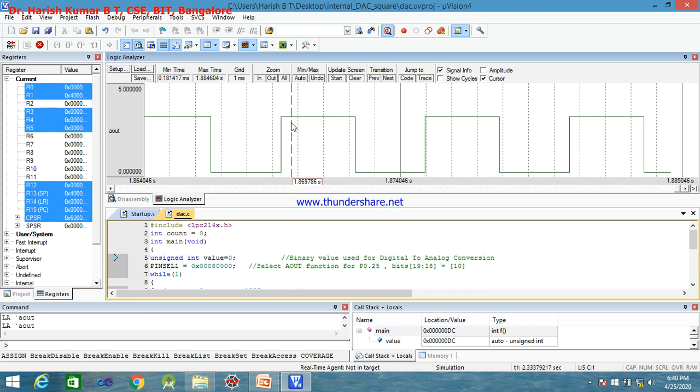Stop. Now what value is this? So this is 1023. That is the maximum value, and this is 0 value. The first for loop, how many points has it drawn from here to here? It has drawn 1023 points, and the second for loop, from 1023 all of a sudden it goes to 0, and from here you have drawn 1023 points again, and this is the square wave. So this is one way of running it. You can simulate this here itself, because this is an internal DAC.